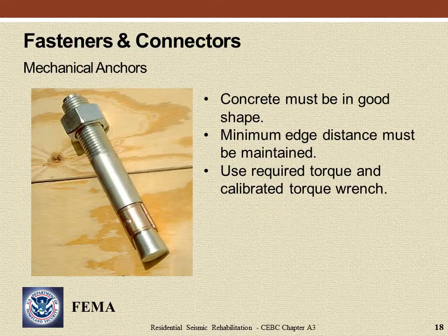Mechanical anchors, wedge anchors or expansion anchors, are one of the types of anchors permitted by CEBC for foundation sill plate anchorage to the foundation. When using mechanical anchors, it is important that concrete is in good shape, minimum edge distances are maintained, and manufacturer's installation instructions are followed, including required torque values.